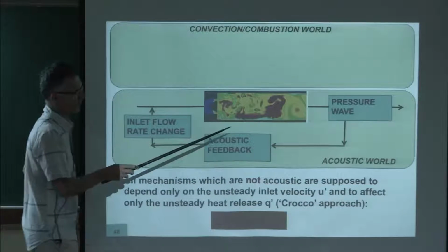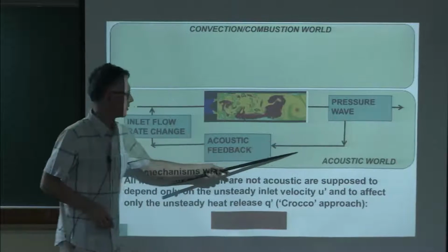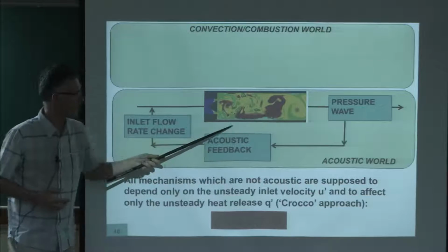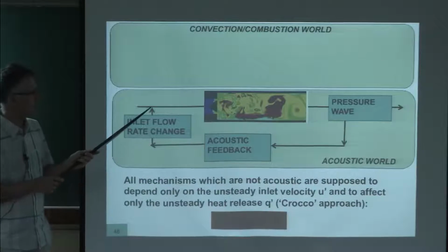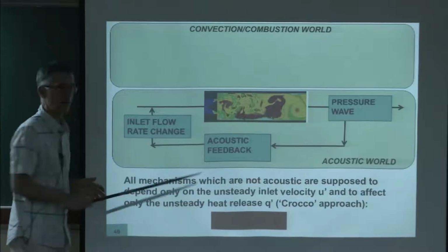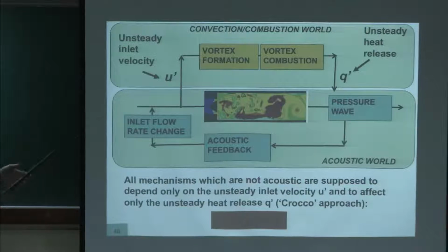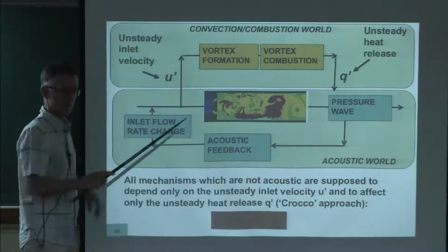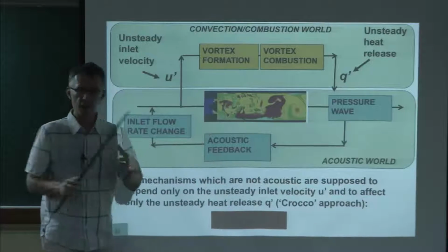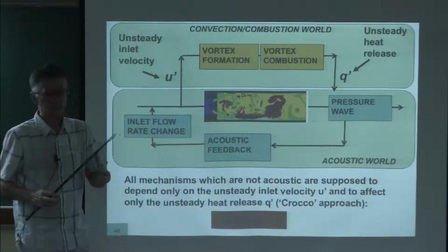Everything here, the generation of the pressure wave, the convection, the propagation of the acoustic in the system, and the change of flow rate at the inlet, everything is acoustic. So this can be completely solved in the acoustic world. On the other hand, the fact that you create a vortex is really a flow problem. The fact that you burn this vortex after a certain time is really a combustion problem. And this is not acoustics.